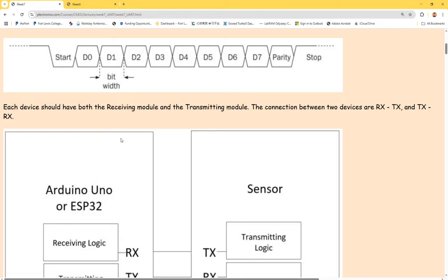So now here's the protocol. The transmitter puts the line down to 0. Okay? So it starts the communication, and that is the start bit. It comes with the LSB, D0, and then D1, D2, and eventually D7 for the entire byte, and then followed by the parity bit.